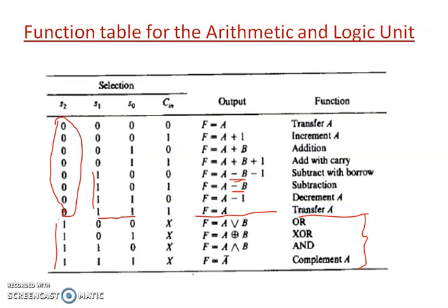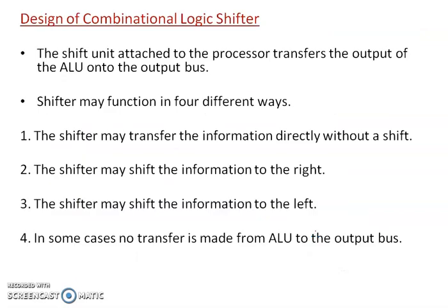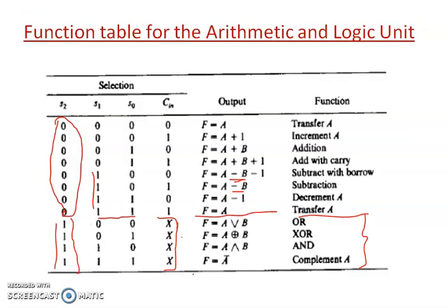One more thing that you can see over here is related to the logic operation. If S2 is equal to 1, then the carry in is a don't care, it won't be considered. If S2 is equal to 1, then the carry in input will not be considered. So don't care. The other things you have seen earlier. So this much is related to the arithmetic logic unit design.